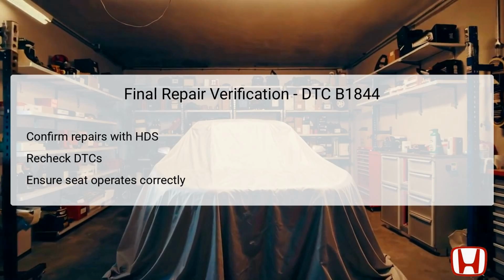In the final repair verification process for DTC B1844, confirm that all repairs and component replacements have been effective. Use the Honda Diagnostic system to recheck for DTCs, ensuring that no error codes are present following the repairs. This step is crucial as it allows you to validate the success of the troubleshooting efforts.